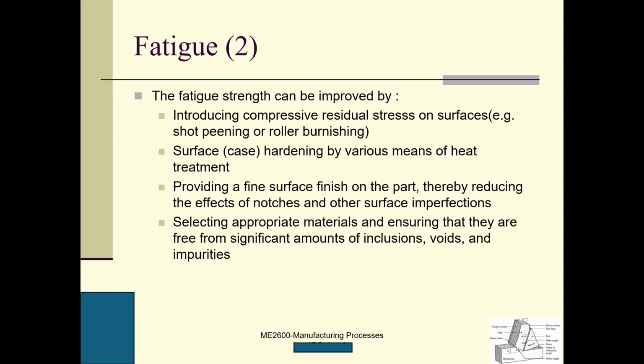So case hardening by various means of heat treatment. Did I tell you about case hardening? Okay, case hardening means that we have a chamber, right? You put the specimen in the chamber, and at the same time you put in something carbon-rich, either liquid, gas or solid, and let your specimen interact with it.